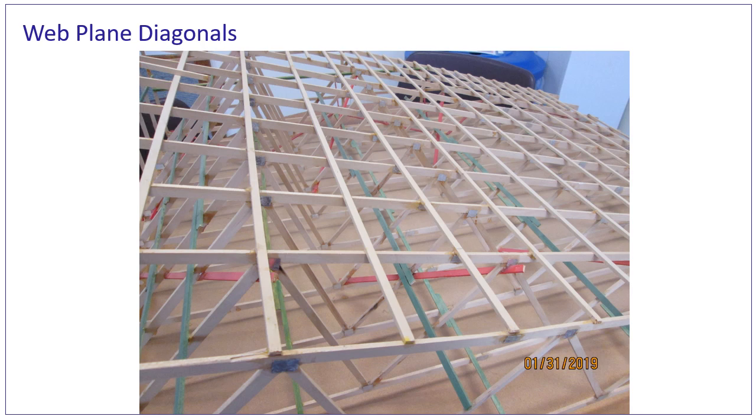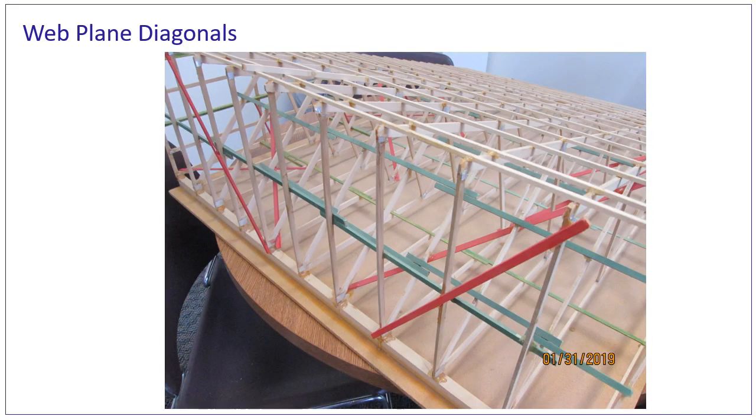Shown on the next couple slides is a 3D model of a large mono truss with the lateral and diagonal bracing. You can see in this view the laterals overlap the truss web by about 12 inches, and the diagonals are crossing where the laterals are located. Note that this is just one way you can brace a system. The BCSI documents have several options you can consult with a professional engineer.